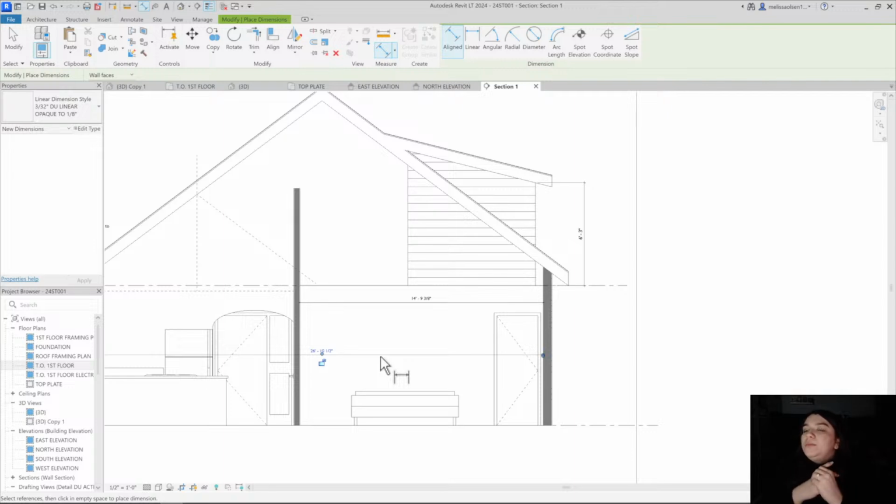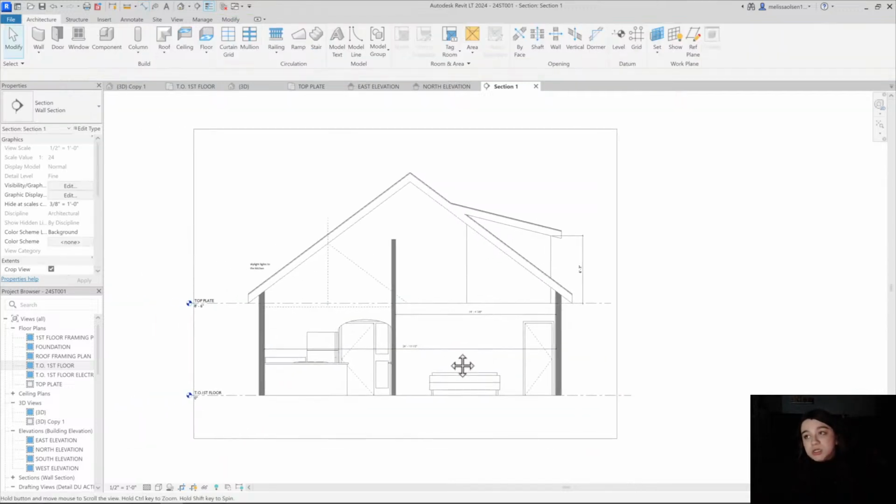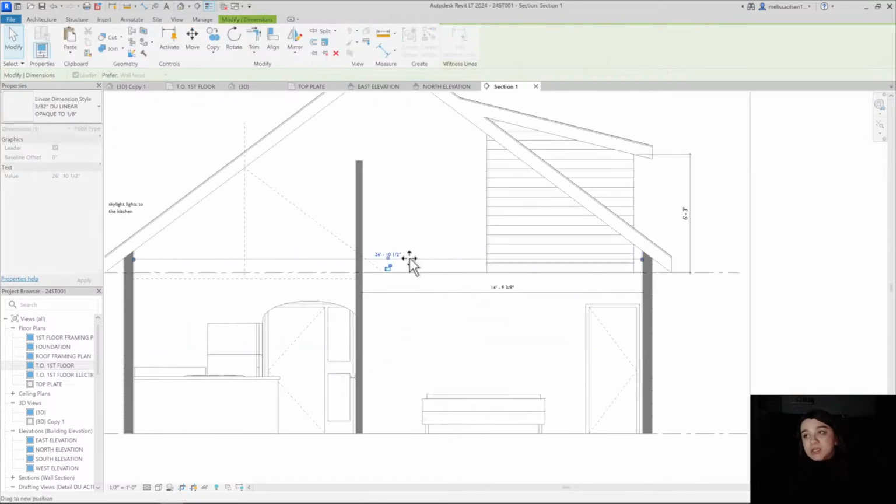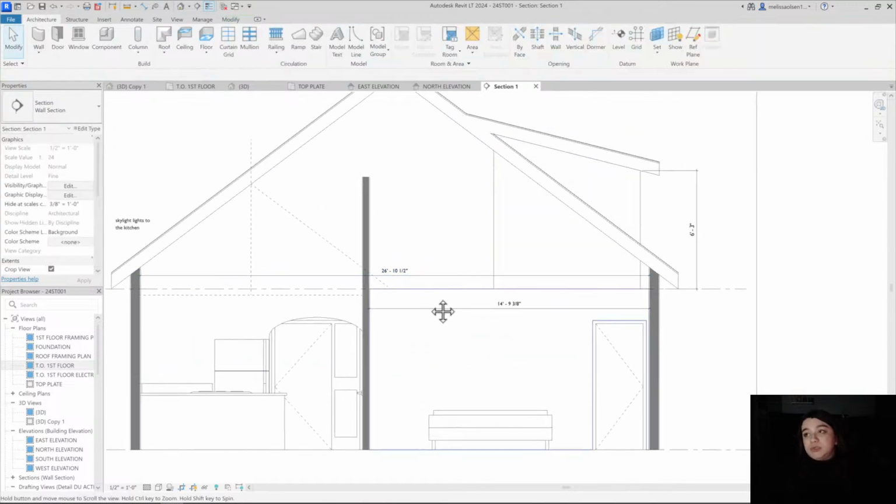The code book in America has general span charts for floors, roofs, all those things. And if you can't do it out of a 2x, like a 2x12, you have to just go and Google I-joists, and companies will have entire pamphlets you can go through, and they'll have their own independent span charts for their I-joist product. So for this it is 26-10. That is a huge span.